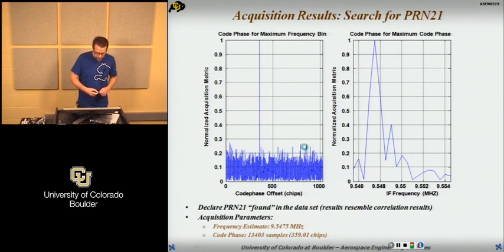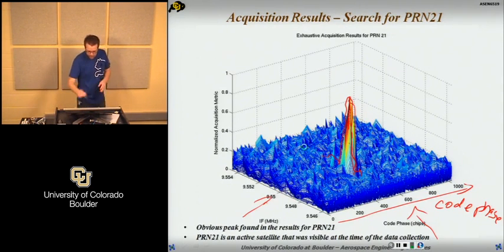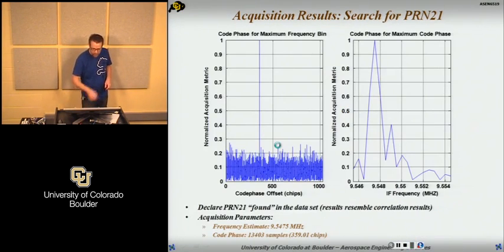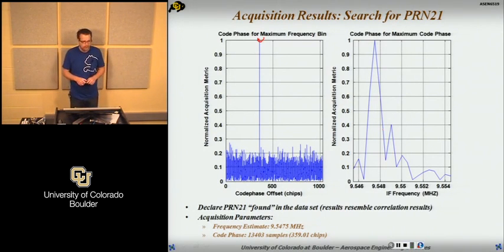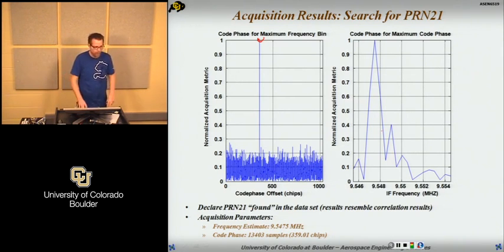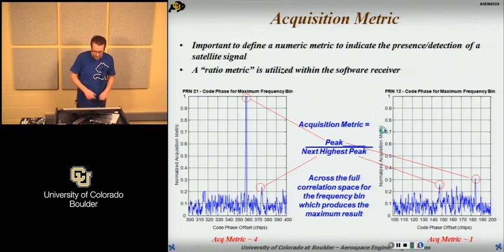And if we take that peak, wherever that was, and look at the two spaces, as a function of code phase for the correct carrier frequency, and then carrier frequency for the correct code phase. So we're basically looking here. Does that make sense? We have this, what is a triangle in the code phase, difficult to see, and this shows a sinc function again. The sinc function is just sine of x divided by x. If you plot that, you see that it's interesting. It shows up everywhere when you have modulation of signals.